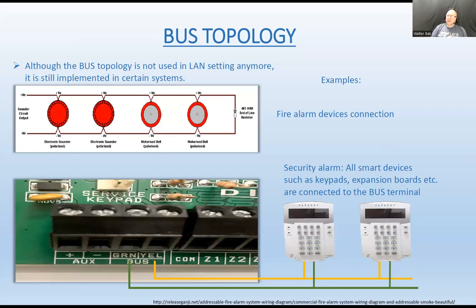So the fire alarms can have many zones, and a zone is basically a terminal, one circuit to which you connect a loop, and that loop can be designated to smoke alarms, all the smoke alarms in that hallway. The other loop, the other zone, can be connected to all the heat detectors in a certain part of the building, and so on.